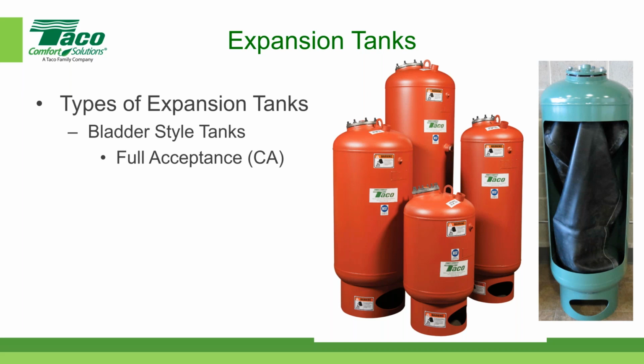Sorry, Rich. Thank you. That does. And just to confirm, the water goes inside and the air is on the outside of the bladder. Correct. So the water enters the expansion tank, and this specific one on the inside of the bladder or the balloon that holds the water, and then between the outside of the balloon and the inside of the metal container is where the air goes.